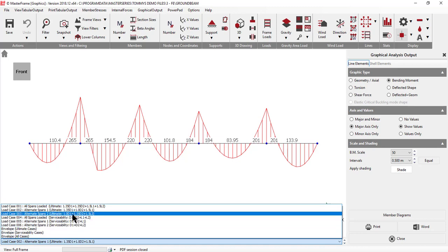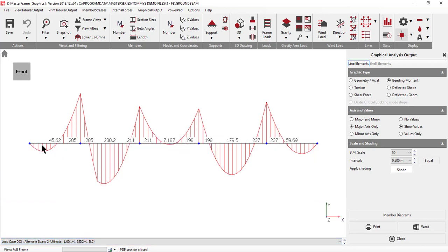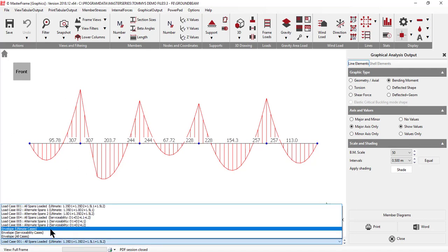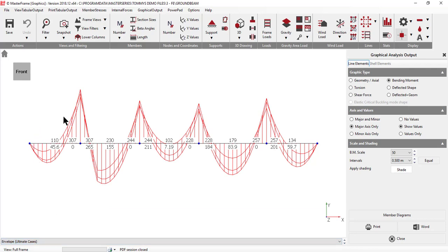and if we then move to the third case, the alternate version of that, we're into minimum and maximum. So we've now gone up to 230, but again we haven't got this support moment any higher, but we're at 230 in our sagging moment, whereas we were 203, which is a difference of around 15%. So it's always important that we do this patterning on our members.